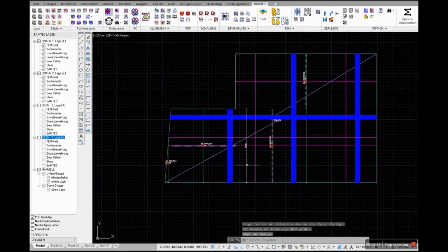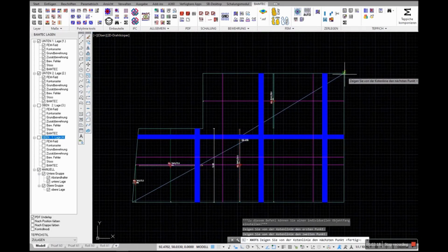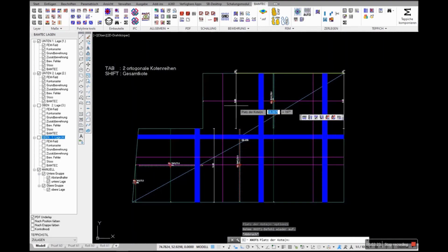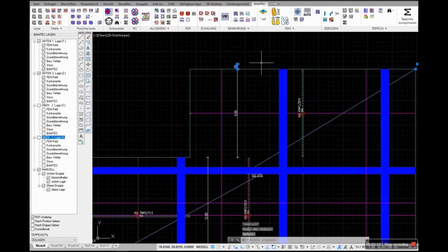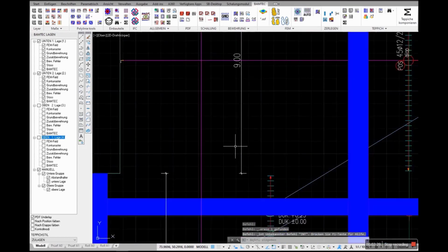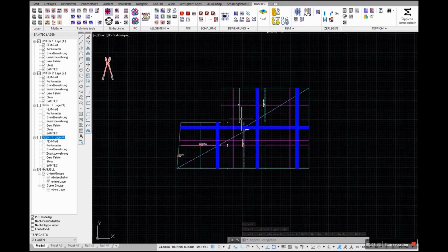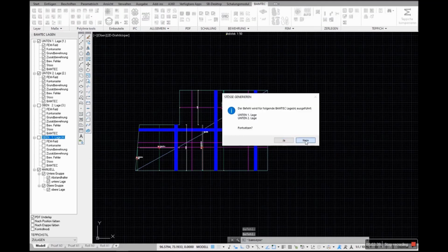These are the basic settings that we use. That means we want to have a bar length of 11 meters, a roll-out length of 15 to 20 meters. That always depends on how many bars we want to have per carpet, and under the parameters chosen we've got a subdivision which optically looks nice but doesn't do justice to what we want. There are still a bunch of carpets that are too short here, as you can see.